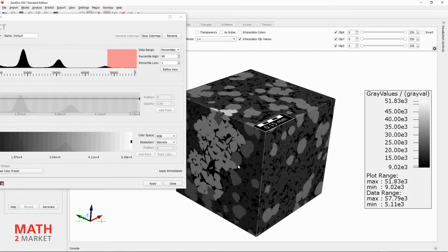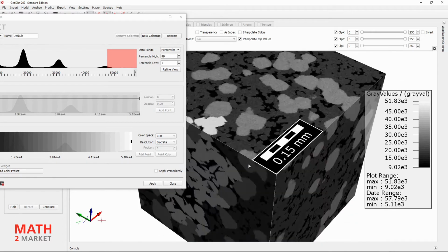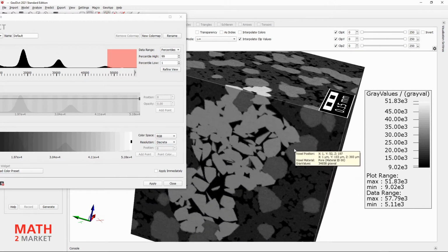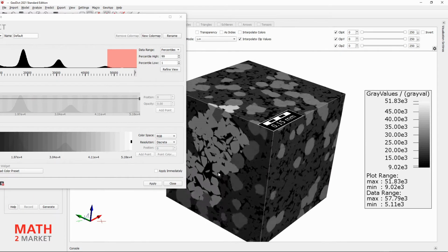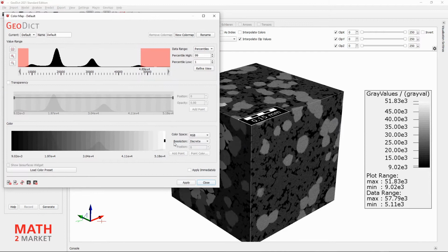Although we can see the different material phases on the domain surface very well, we have no insight into the inside of the dataset. Our goal is to clearly bring out the white and light gray material phase. We will try to present those two in a particularly precise way, while still allowing us to take a look inside. For this purpose, we want to define a custom transparency transfer function.